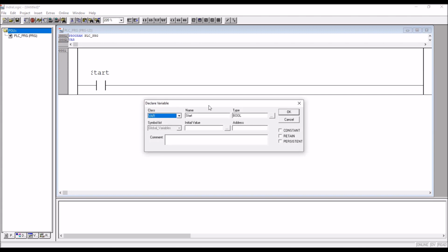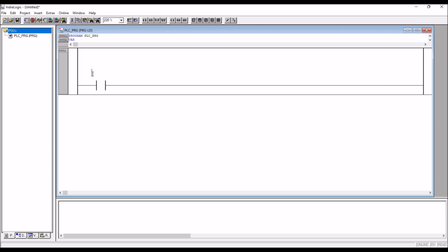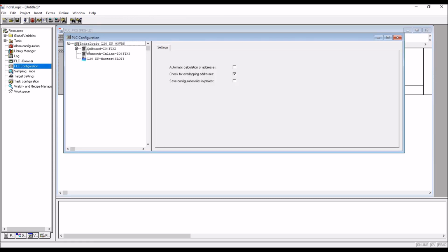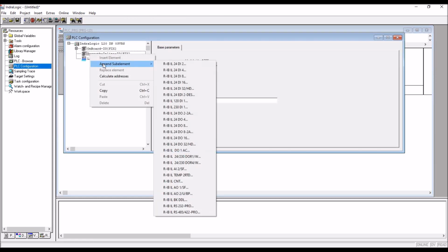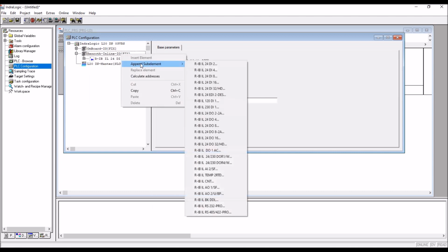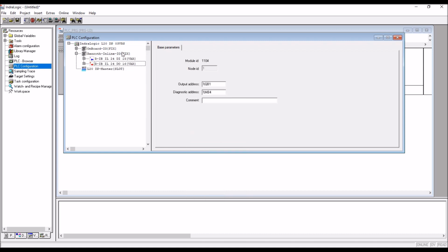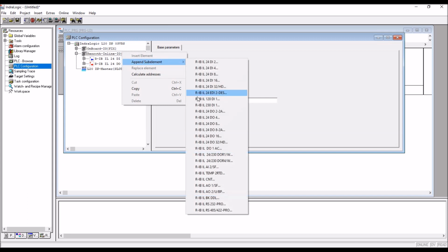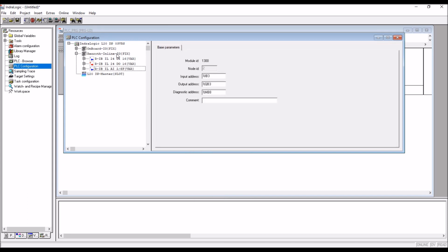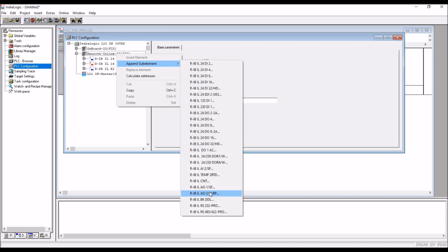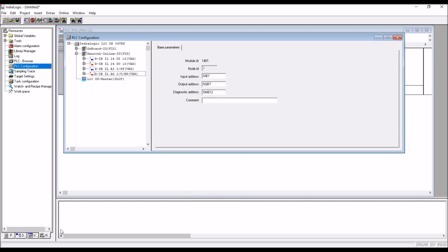And so what is the address we want? We want to have, say for example, inline. So inline means we should have inline modules. So go to Resources, PLC configuration. So the usual procedure, adding the inline modules, DI16 first, DO16, AI2, AO2. Okay. Now go back.